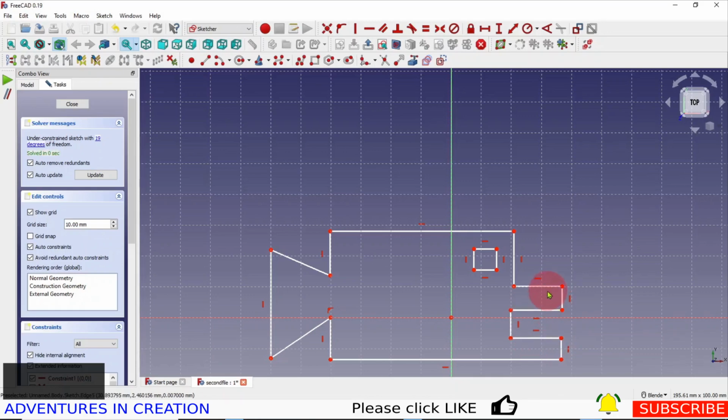It's where it's going to be when we finish up. So again, from an alignment standpoint, one of the things I notice is that this line and this line should be aligned. So I'm going to select that point, and I'm going to put a vertical constraint. And now those two points, those lines are actually aligned. So it's going to keep them in sync.